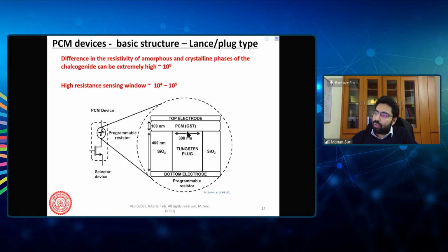However, in the amorphous state, it would be very high resistance, almost non-conductive. So you don't have any path for current to flow through this entire stack. If no current can flow through this entire stack, any idea how you ever achieve the Joule heating and subsequent crystallization?